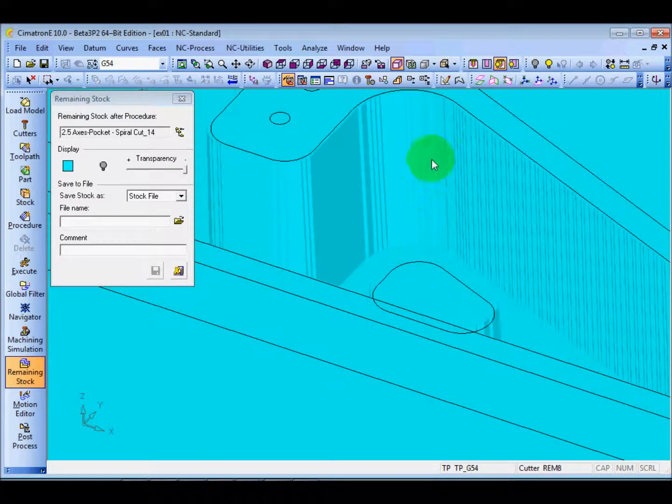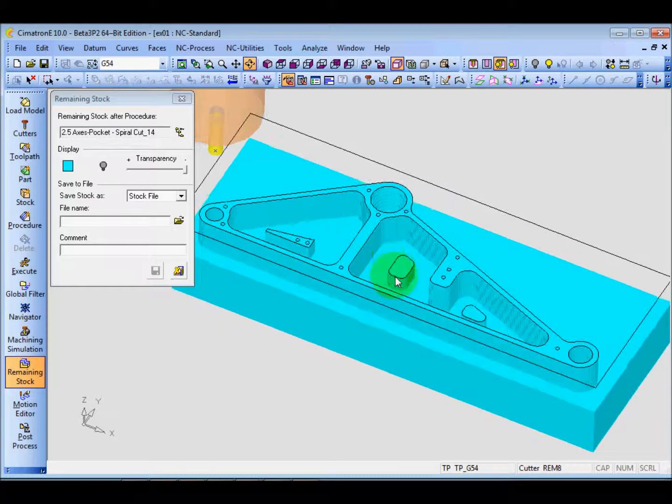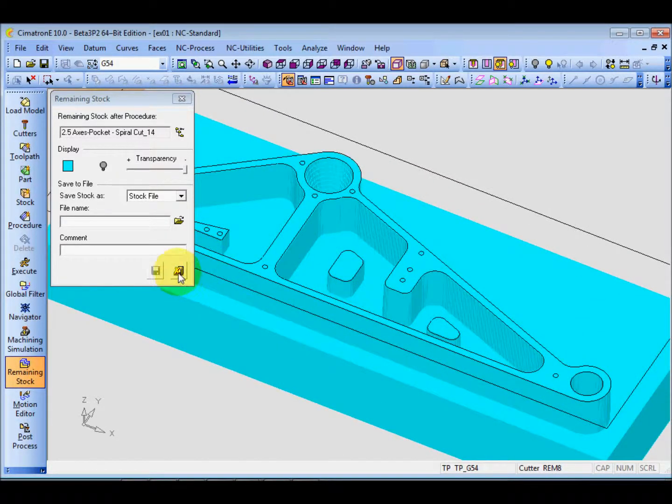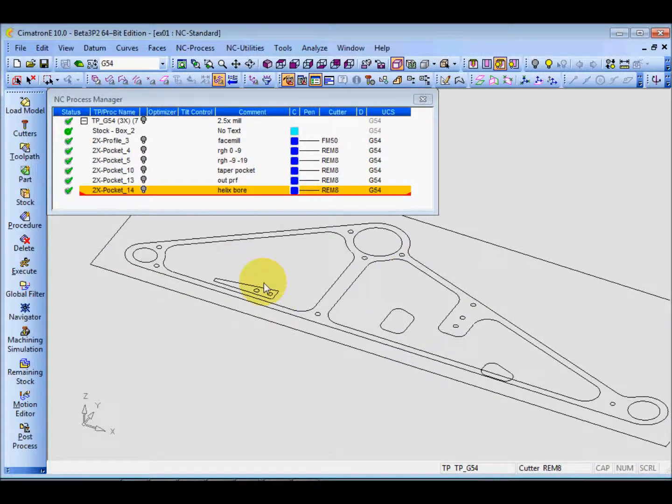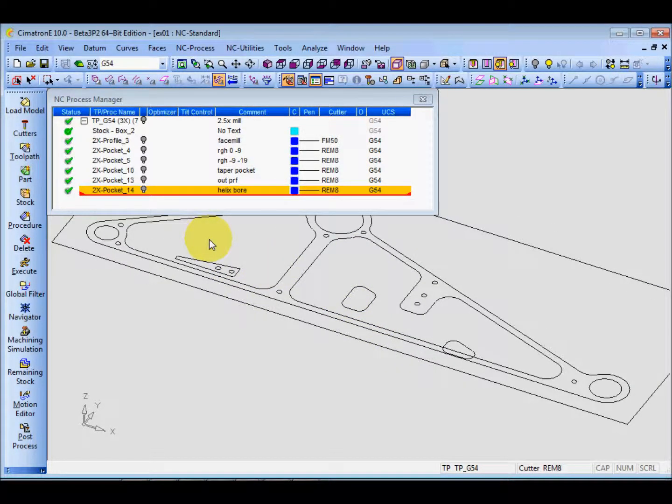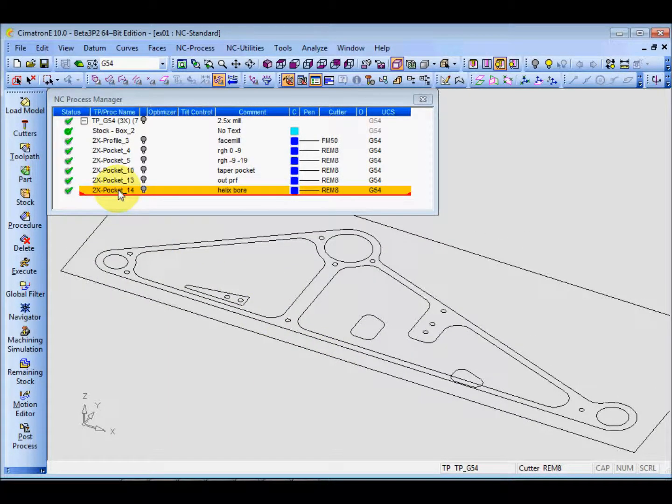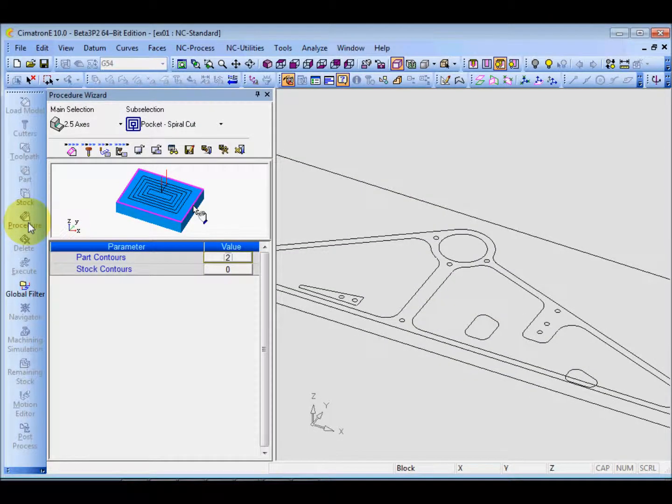finishing bottom. So now we're going to do some finishing at the bottom of the finishing on top of the island. So island, yeah. So for this, let me highlight this and create a new process so that it can be located under this create procedures and the part contours.